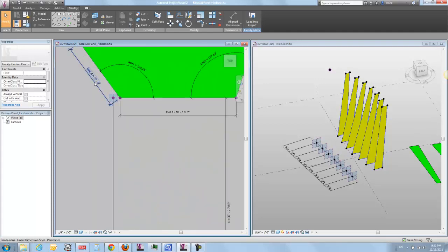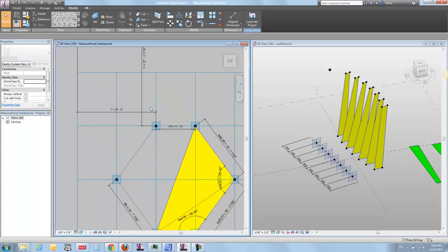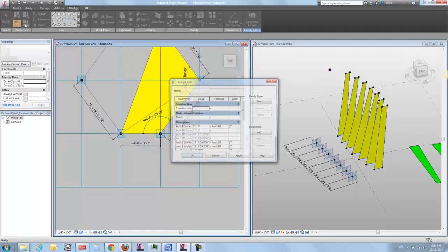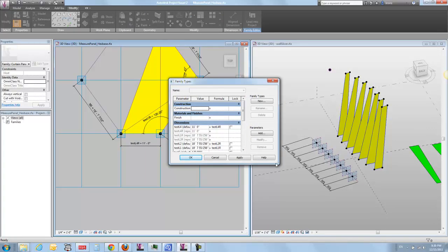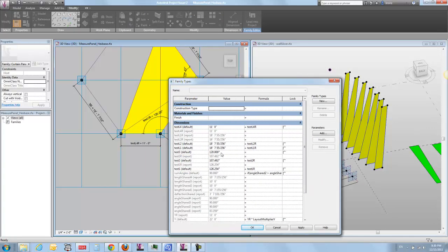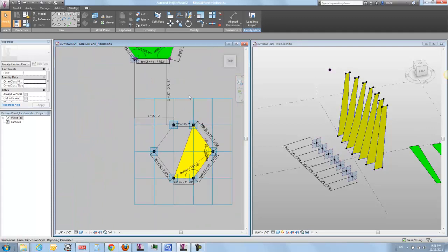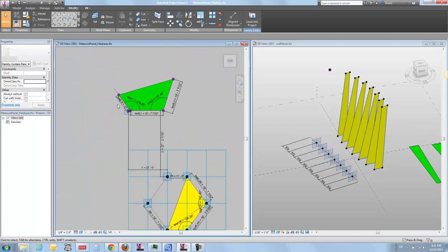over here, this one, which is 11 feet, and this one, which is 11 feet. If I look at my parameters, you can see I've got test L4, which is the number I've given for that parameter, driven by a reporting parameter. What that means is that for every distance over here, I'm making a duplicate length over here.